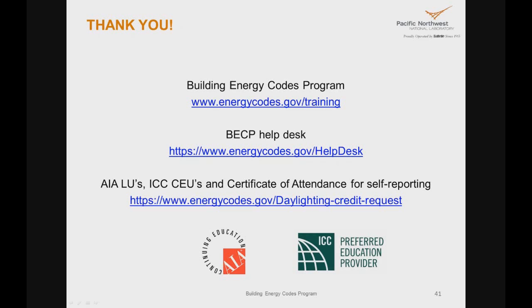There may be some requirements tied to the envelope section, where I'll have to look in detail. If you do certain higher window to wall ratio, you may be required to put in controls, or if you have skylights in a zone and so on, you may be required to put controls. But at least in the lighting chapter, the daylighting controls are not required. They are optional. In the 2012 IECC for daylighting controls, or all the provisions you've talked about, is commissioning and testing required?